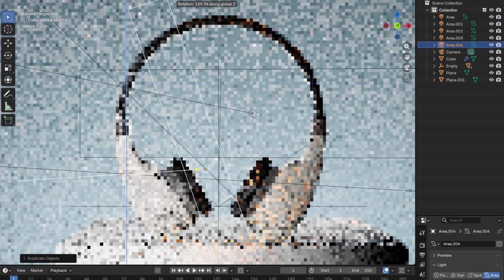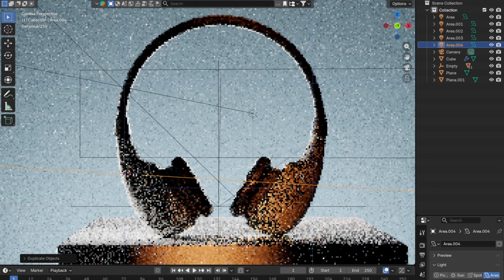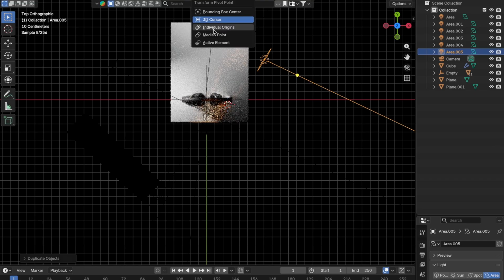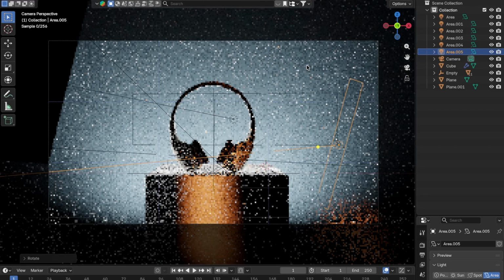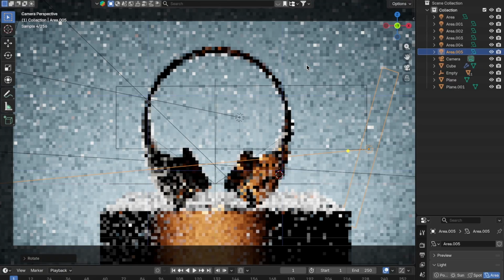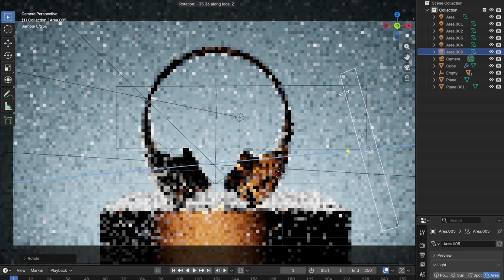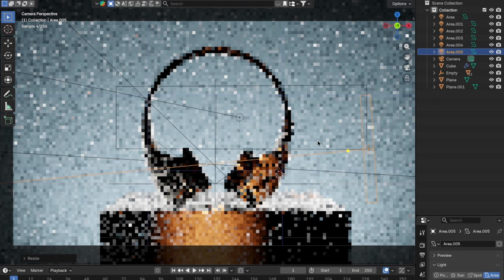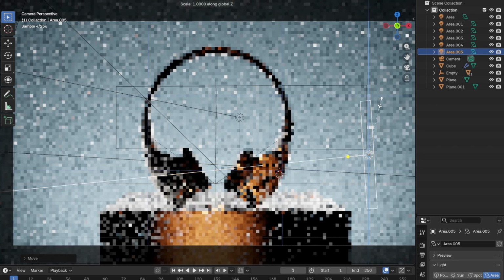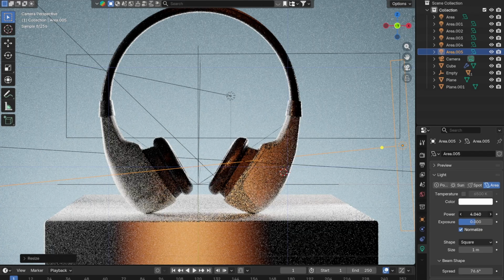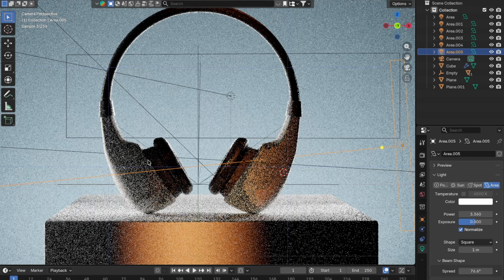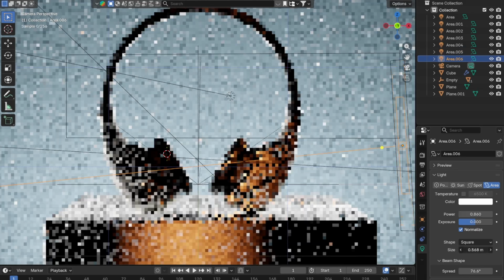Perhaps this method of setting up the light is not entirely correct, and it will not be suitable for animation, but nevertheless, detailing the light and emphasizing all the details and small objects in our scene is very important for the picture to turn out precisely cinematic. We duplicated the light, made it even narrower, and placed it on the right side in order to make room from behind. Yeah, and the combination of our orange light with the white light allows achieving an interesting result.